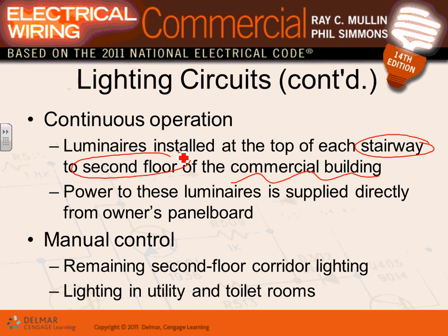Continuous operation, 24/7. So the stairway, typically, power to these luminaires is supplied directly from the owner panel. You just take a circuit breaker and you put it on a light and let it roll. 20 amp circuit, let it roll. No control whatsoever, 24/7. With the energy code, guys, you might not get away with all of it, but remember, lights in the building, you don't want the building to be too dark either. So sometimes they just leave one or two fixtures on in the hallways all night to make it not look ghostly. So that's exactly a good example. For security reasons inside the hall, they want the stairways to be lit at all times. Security as well as safety.